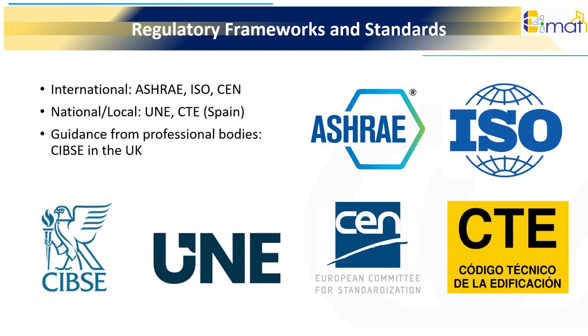Material properties are guided by international, regional, and local standards. International: ASHRAE Handbook, ISO 10456 for thermal properties, ISO 14040/44 for LCA, and CEN/TC 350 for environmental performance.